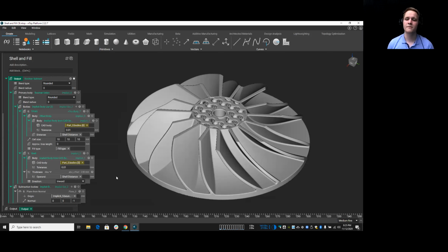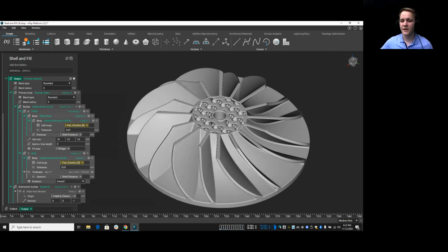Looking at it in its totality might be a little scary, but trust me, it's about 2 minutes of work. But let's assume that I need to find the best shell thickness in combination with the best infill. That means I'm going to have 50 or 100 different iterations of this that I'm going to test, whether physically or through finite element analysis. Either way, what I really don't want to do is all of these steps on the left 50 to 100 times for every single new iteration.